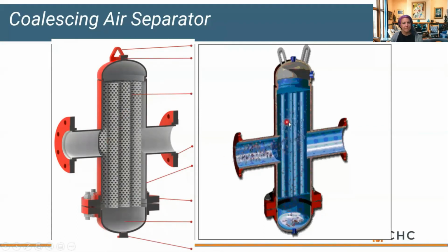Just for reference, this coalescing is about 3 times the cost of a standard tangential style air separator. So it's an investment, but it is definitely more efficient than a standard Rolairtrol or tangential style.